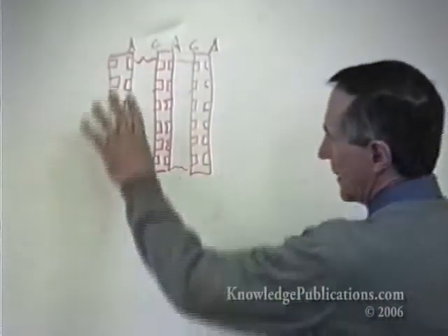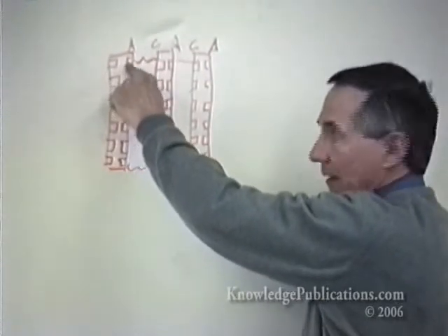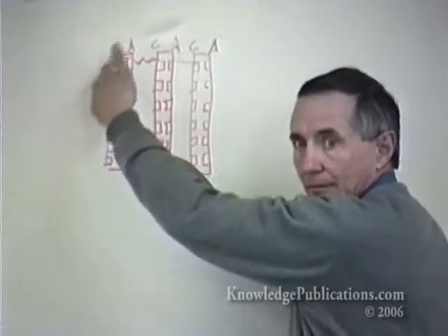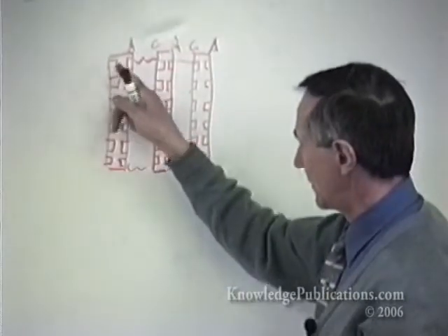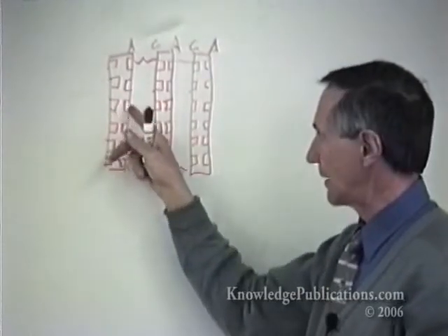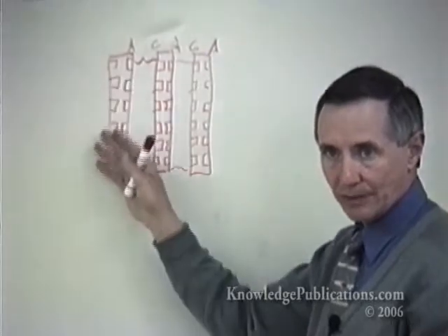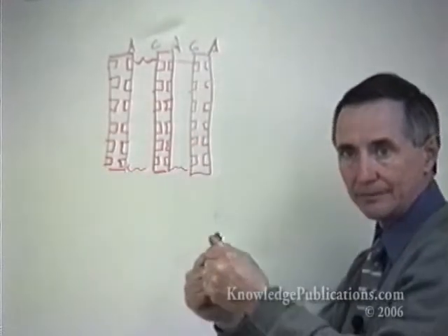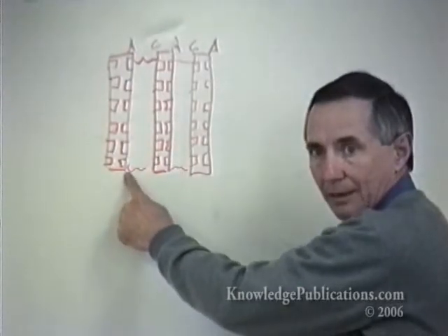And the result is that this makes the occasion of bringing the hydrogen to this one and the oxygen to this one. And you might think of this as a spiral. If this was a circular disk, you might choose to have this on spiral geometry so that you'd feed it in here, and it would disappear in the middle. It would feed all of the area and disappear in the middle. And you could do it either way. You could do it from the inside, and the next one you can make it from outside feed or central feed by your choice. But the key is that you would have a compact stack that you could put in compression and make sure that it didn't have a way for hydrogen to leak out, because you could form the gasketing right out of the system.